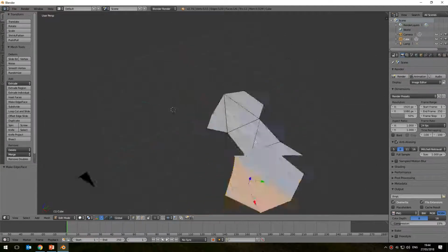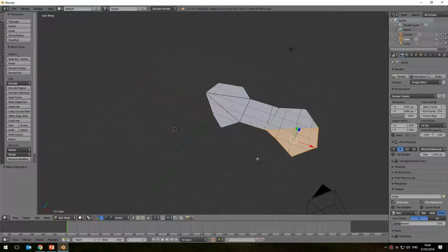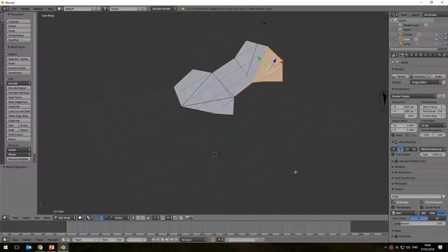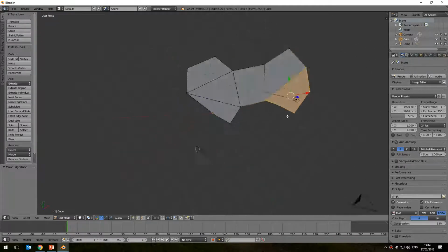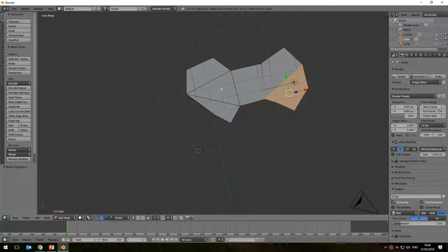So what we need to do now is to extrude again, so to stretch or pull something out. But this time, instead of doing it with the corners, we're going to do it with the faces. So we need to just change an option down here. You'll notice on this same toolbar, this is the only toolbar we've been using so far, you have 3 little buttons together here that look like our little white cube did at the beginning.